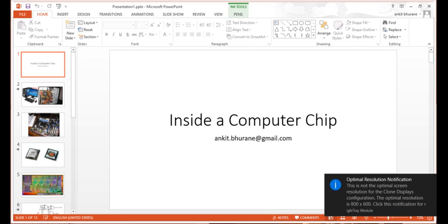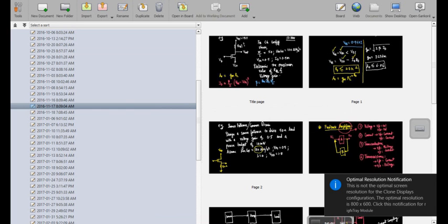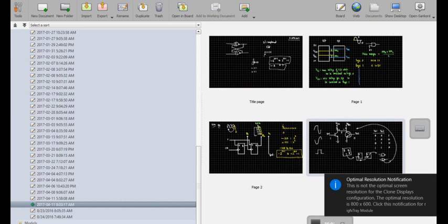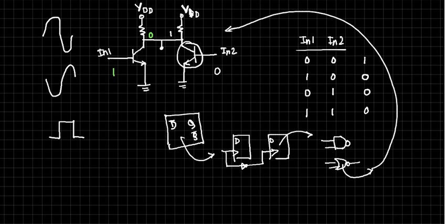4 series are usually the CMOS series. Okay, so based on the series, you determine which kind of implementation it will be. And you have gone through various data sheets. You should be able to answer that. You didn't ask me such questions, so I didn't answer. You should be curious enough to ask what is LS. So LS is what is called low power Schottky.